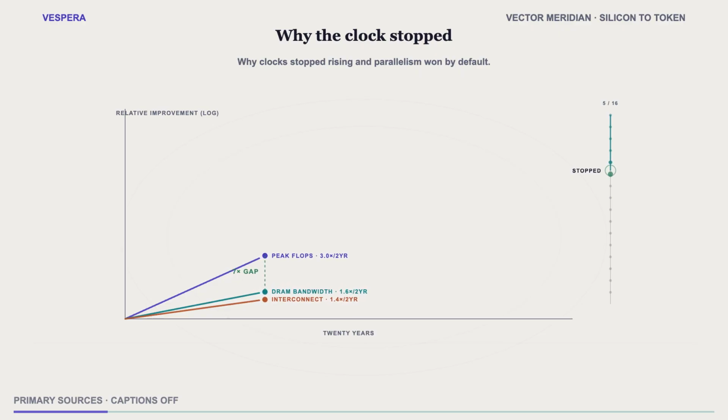Around 2005, Dennard scaling ended. The reason is a detail of physics that refuses to cooperate. To keep switching quickly, you need the supply voltage above the transistor's threshold voltage by a comfortable margin. But threshold voltage cannot keep scaling down, because as it falls, transistors leak: they conduct when they are supposed to be off. Leakage is power spent achieving nothing, and it rises sharply as thresholds fall. So voltage scaling stalled. And once voltage stops falling while density keeps rising, power density starts climbing. Push the clock higher, and you get a chip you cannot cool.